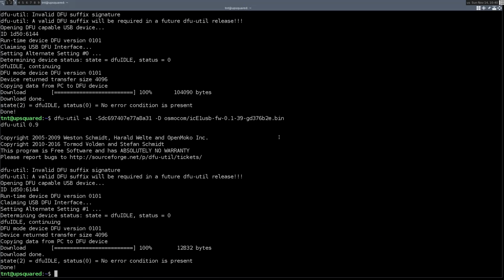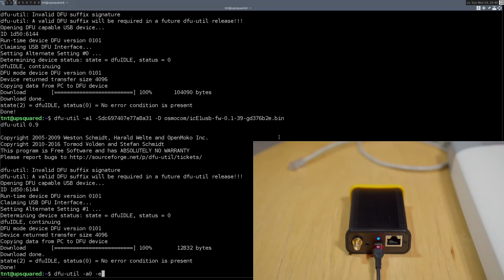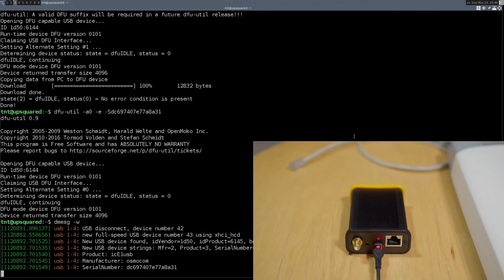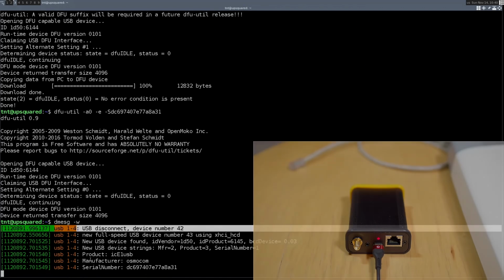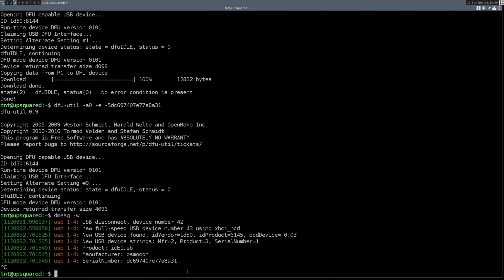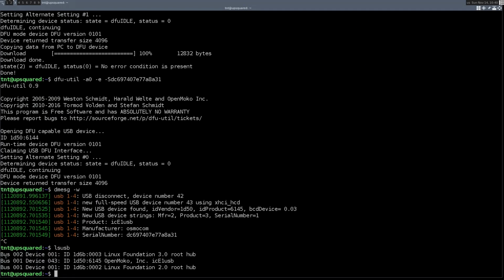After the flashing, the device needs to be reset, either by unplugging and replugging, or using dfu-util again to send a detach command that will trigger the reset. The front side LED should go back to either red or green depending on whether an E1 link is already connected or not. Now that we have an up-to-date device and it's properly recognized by the OS, we can get started with the host software stack.